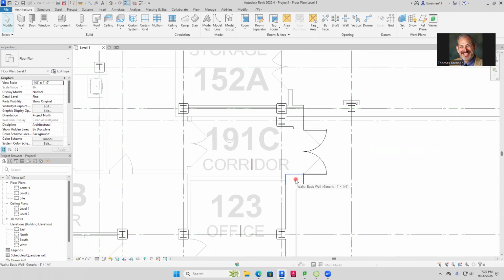The way you do walls in Revit, you never make gaps for your doors, you never make gaps for your windows. The reason is Revit was written to do that, so the doors actually carve out their own hole, and so do the windows. You actually confuse Revit if you stop the wall, try to put a door in, and then go through it. So you just draw your walls all the way through right now.